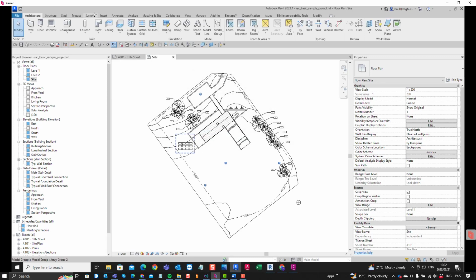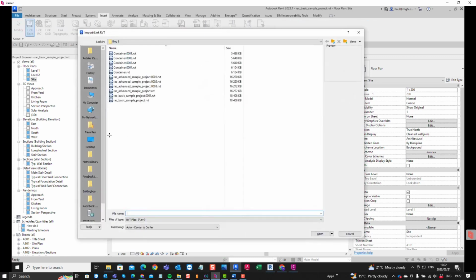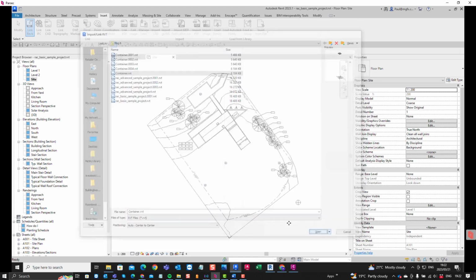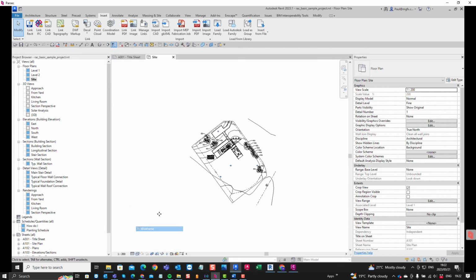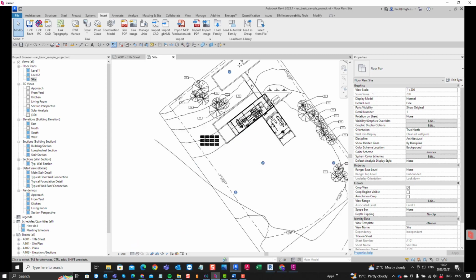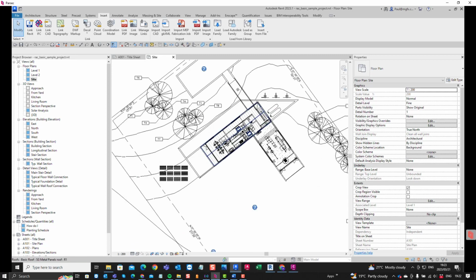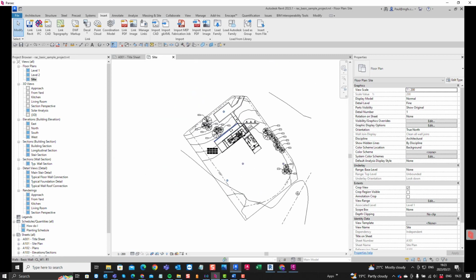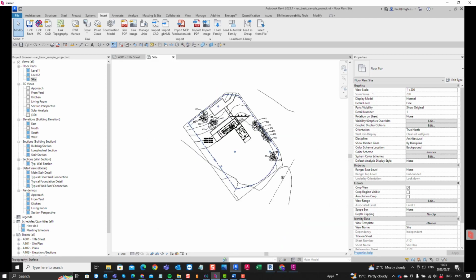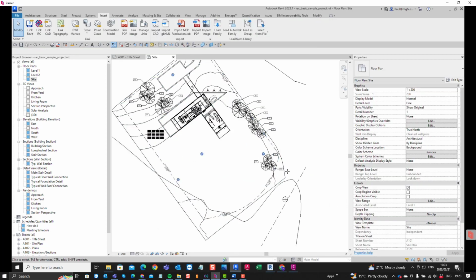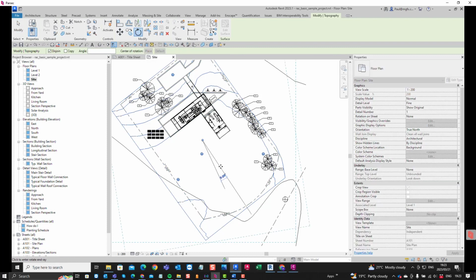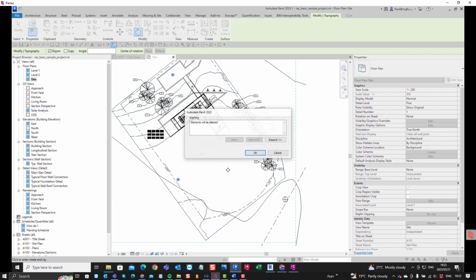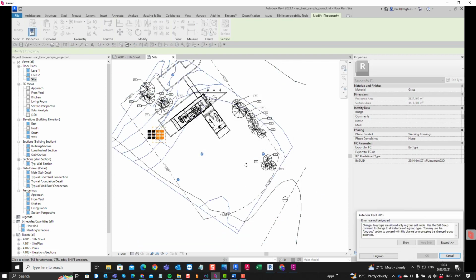That's our view range. We insert the Revit link. We choose the container file, center to center. Right, we can view that in the appropriate manner there. There's our site, and there is our little design. So in this case, actually, it's not badly positioned, but again, we could rotate. We could rotate this design based on whatever orientation we would like.